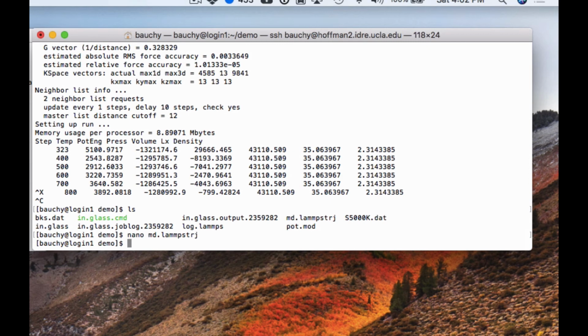So here the simulation will just continue, and it will most likely take around 8 hours to finish if you choose around 16 processors. In this case, I chose only one processor, one core, and only 1 hour. So the simulation will just stop before it has the chance to finish.